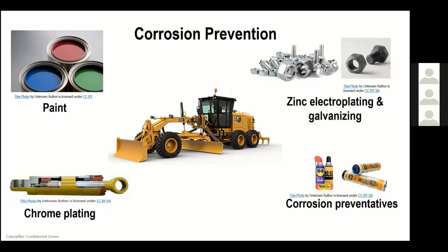All right, so how do we prevent corrosion? Probably the most common is painting. So we paint things to make them look aesthetically nice, on different types of components. And if you're building a deck, or using certain types of materials, you want to use things that are zinc electroplated or galvanized. People put up sheds, they'll use galvanized that has a lot of zinc on it. I'll talk a little bit about some of these, but by putting a plating on there, you're essentially putting zinc on, and the zinc is going to oxidize. It's going to form kind of a white precipitate, but it's not going to be as ugly as the formation of rust or the bleeding of that orange color that you'd see.